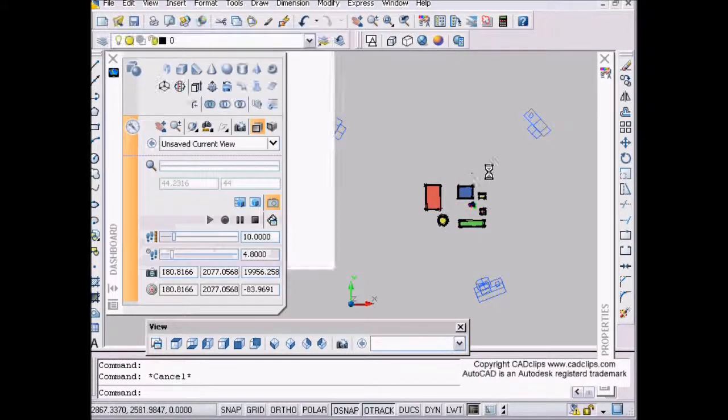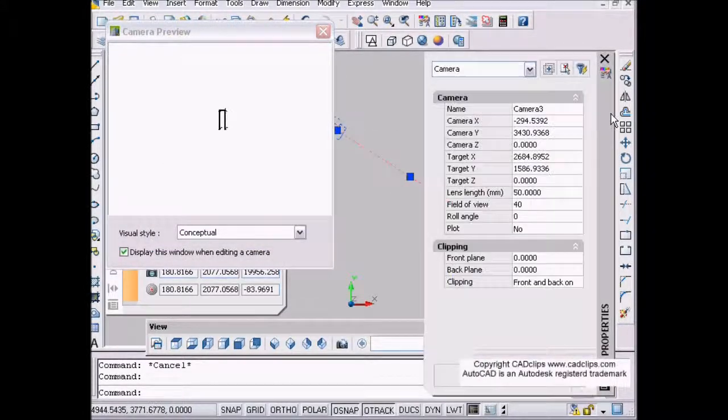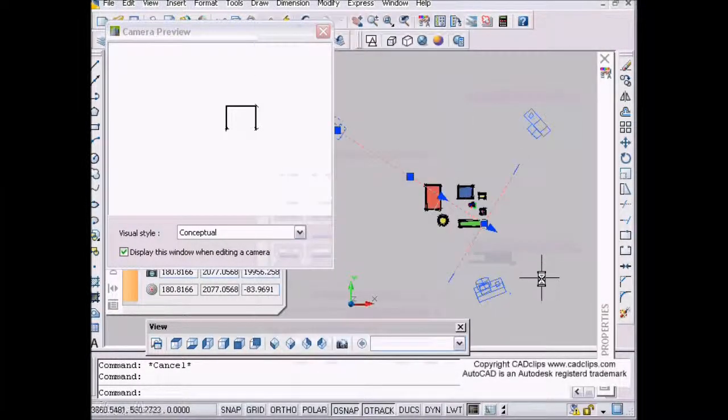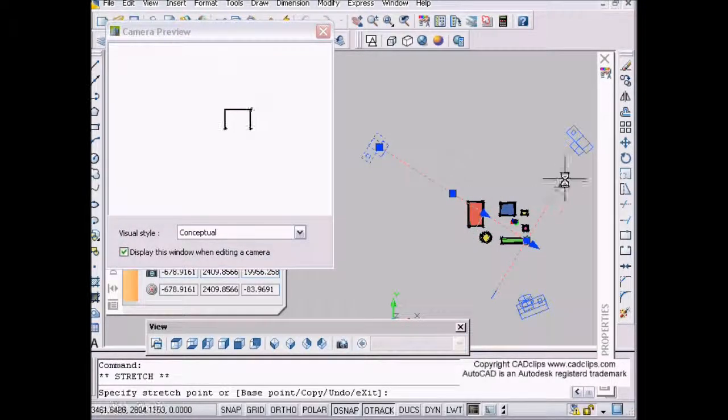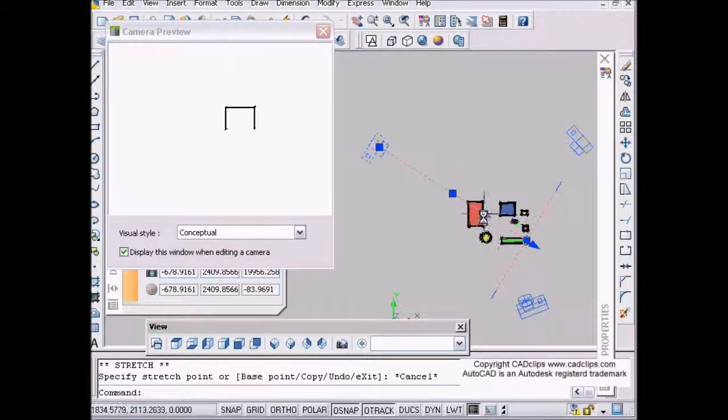So what happens there is we can click on that camera now, and we can set those clipping planes to be a certain distance away, by adding in some numbers, 500 and 1000. Okay, it'll capture part of that. Or you can go in and use your calculator as well. So you can add those clipping planes, and a front clipping plane is the front one, and then the back clipping plane is the back one.